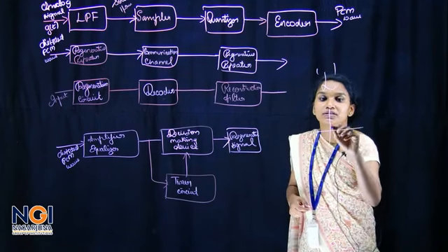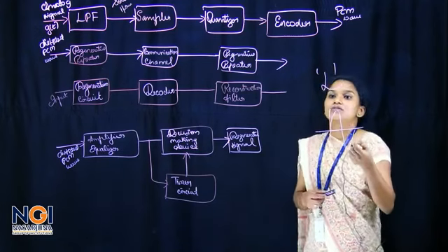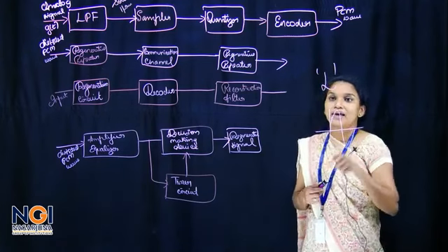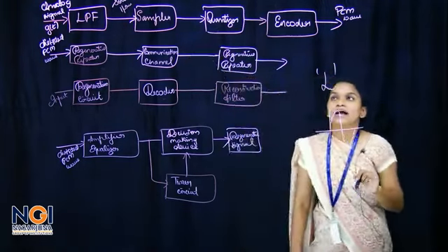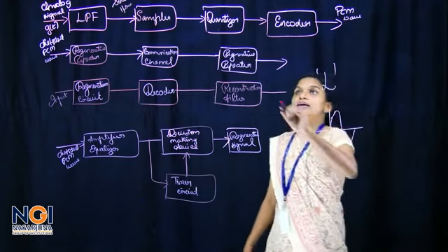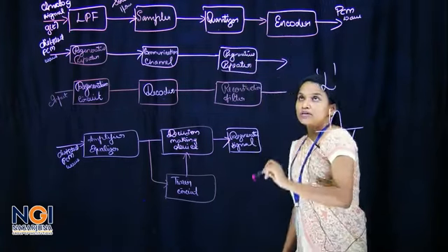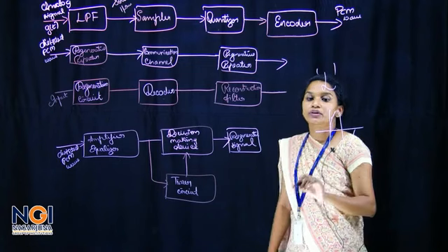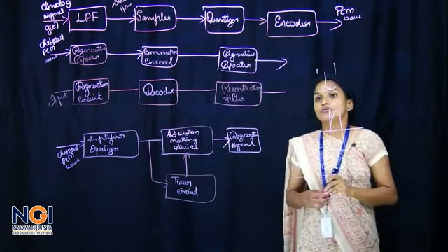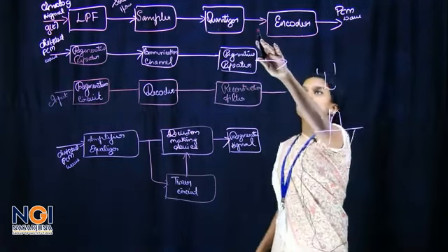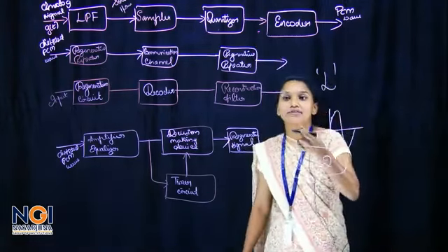We have some analog signal here. You choose a few points on this analog signal and round them off to some stabilized value. The quantizer takes each sample value and rounds it off to some quantization level. Once the information is sampled and quantized, it is encoded into an n-bit code word. The number of bits in the code word should be related to the number of quantization levels. So the various binary levels are encoded here.